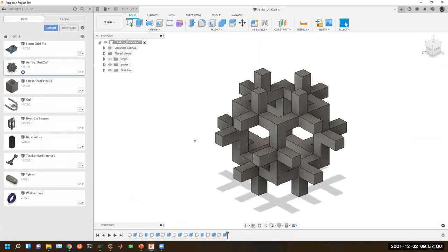So if you want it on the unit cell, what you would do is create your unit cell still in a rectangular shape, and create the shape that you want, and then apply a scale factor afterwards to create your unit cell with some sort of squish or deformation to it. And that way, whatever your unit cell looks like in this unit cube is what that base unit cell is going to be.